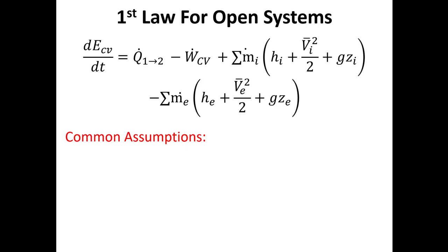So when we go through each of these components, basically we're going to treat this problem like Lego and analyze each separate component inside our thermodynamic cycle. So for each one of those components, we can do a first law analysis. In a first law analysis, we'll start with this open version of the first law because mass is flowing through each of these components.